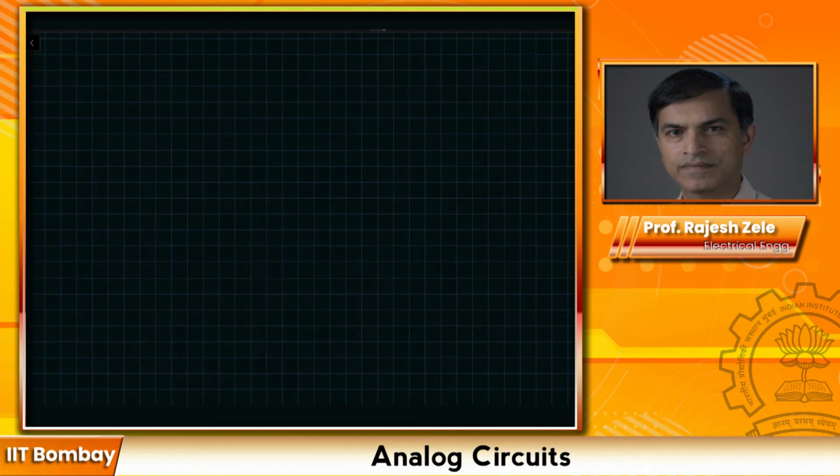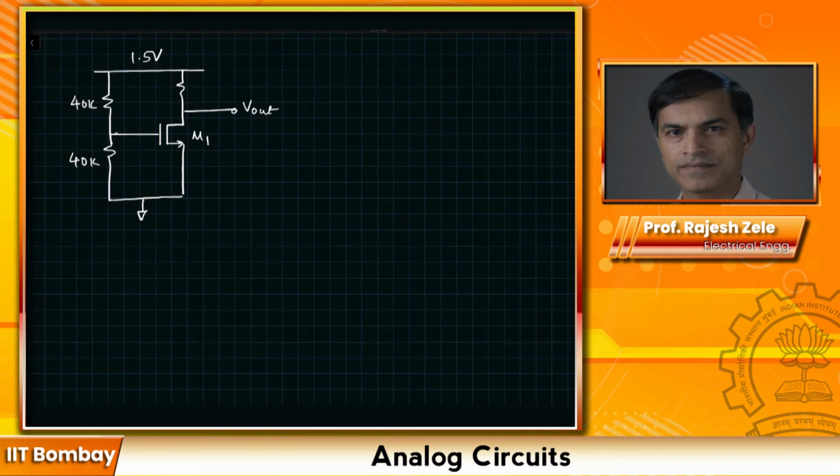Now I'm going to make a small modification to the circuit. Just like before in the bipolar case, I'm just going to move the decimal point of the drain resistor. So we are going to go from 7.33K to 73.3K ohms.